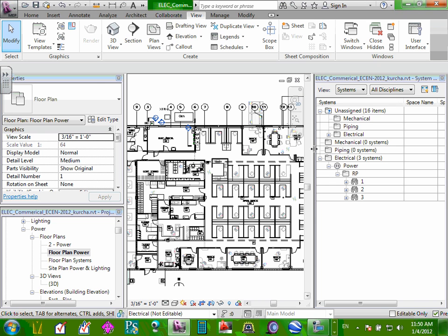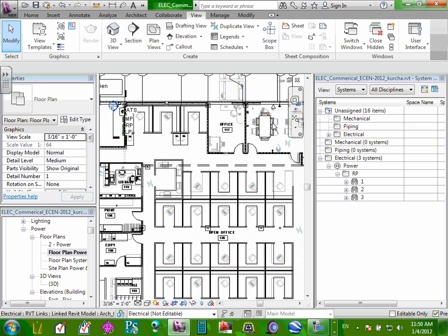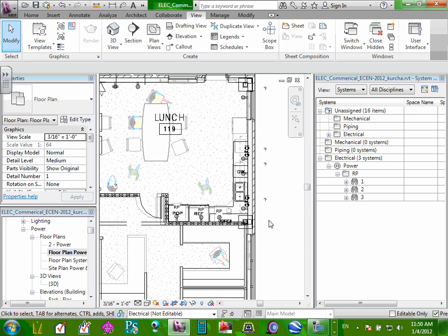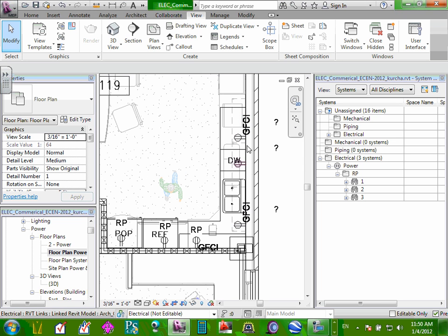Why can't I size these? I'm going to move this one to the side because I'm sizing here. And I'm going to go back to my interface here, guys. There you go, right in here. Now, do you guys remember that I have two receptacles here? One of them, remind me, this is not the dishwasher, the one above it, what was it for? The microwave and the extra receptacle, I'm going to put them in one circuit, okay? So that will be your example.